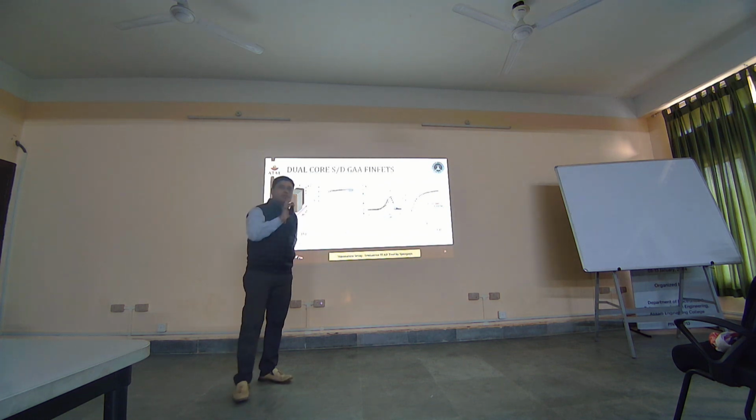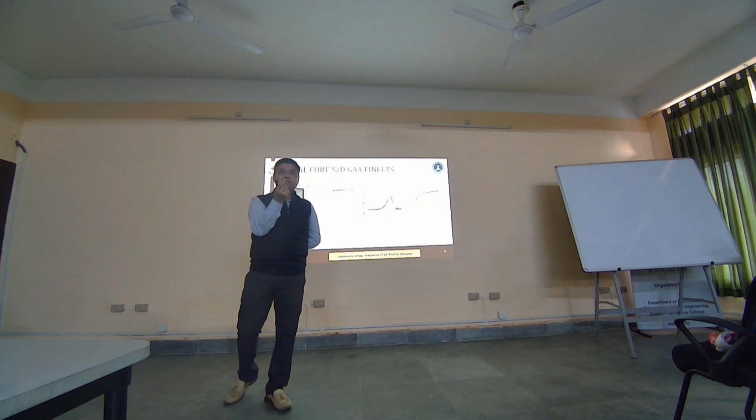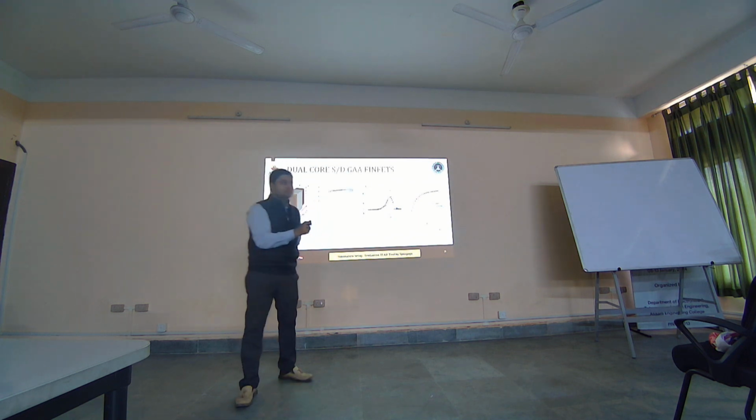Although there are many articles where you will find the exact match, most of them may also be having some parameters which they were actually not supposed to tweak. For example, you cannot tweak the band gap of a material, right? Because it is constant. So while selecting calibration techniques, you need to see which parameters they have varied, whether it is a material dependent parameter, whether there is flexibility of varying it, or they are just varying it just for matching the curve. So that should be kept in mind whenever you are going through articles where calibration is discussed.